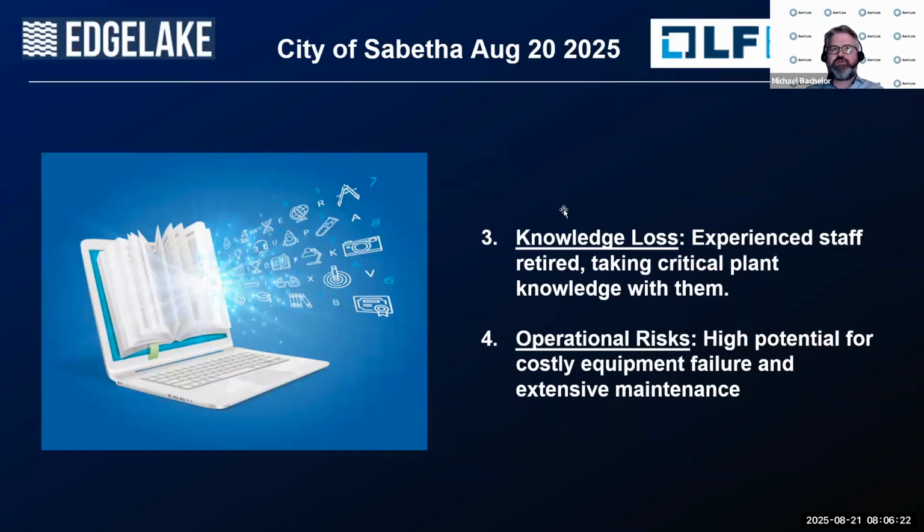And then there are further operational risks or costs, I should say, that aren't as high as a clear well going dry, but they still matter. And one such case is wastewater has blowers, and they'll work more often as you have more influent coming in, and less often as you have less. Where the sensor is located to sense it can be fooled, and so they're struggling with the physical location, whether they can change it. But in a downpour, you're running constant because it thinks it has to, and that can wear out a $30,000 to $40,000 blower. So that in and of itself is a value add to the budget to look at it as well.